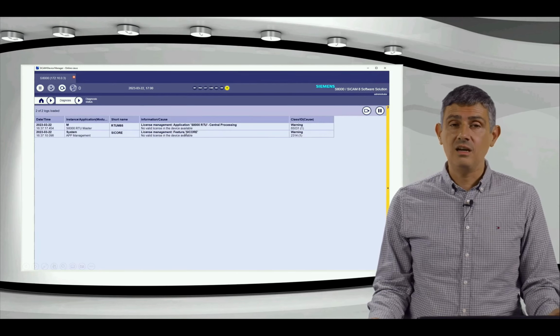Now, you can also select for the measurements, even though they are not really in the alarm and event archive. Here you can select the scaling that these signals will have in the HMI and the unit that will be displayed in the HMI. This is quite important. You can have different scaling, for example, for currents, and a different one for phase-to-earth voltages, another for phase-to-phase voltages, another for frequency, and so on. So in this way, you can select how every signal will look like in the Sicam HMI.